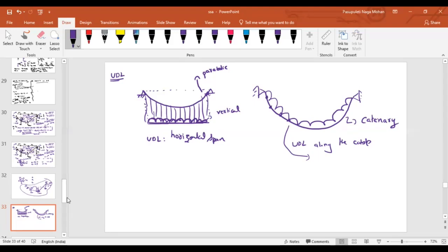No. The direction of the loading also depends upon the slope of the profile. And again, I'm telling you, solving this will not be completed within 5 minutes. So you only need to know that if the UDL is acting along the cable, the deflected shape will be different. More than that, going through it will be a waste of time. No competitive exam will ask you this type of question, but for the parabolic case they can ask, because this can be solved; even though it might be complicated, it can be short.